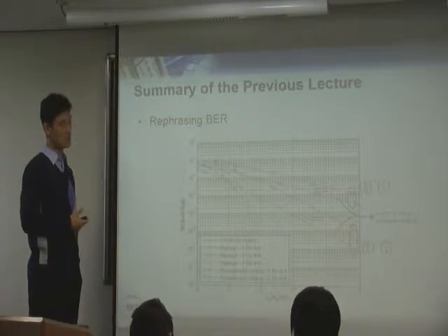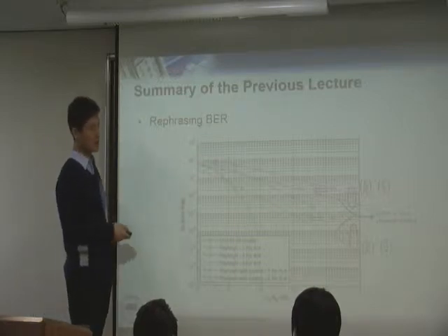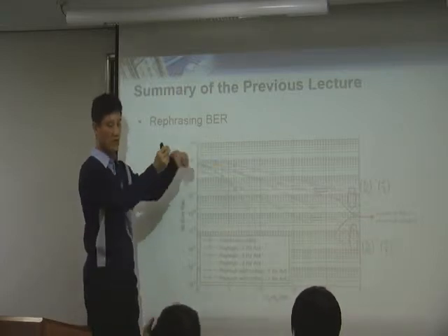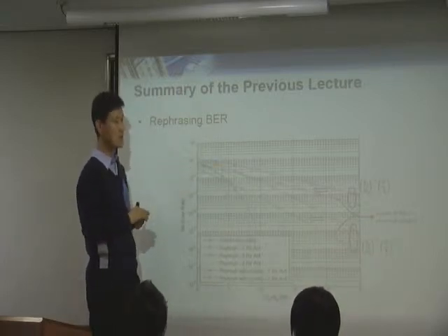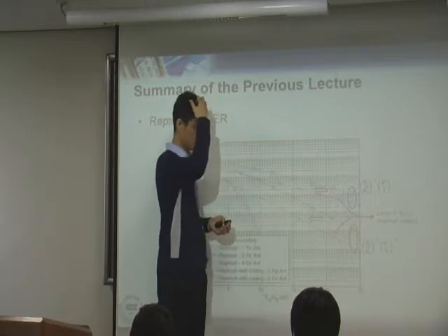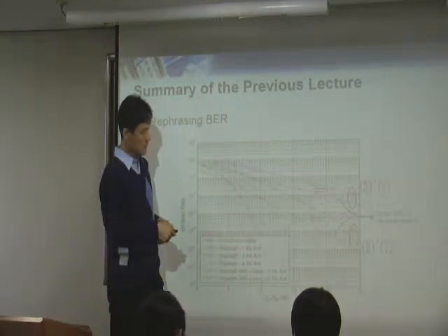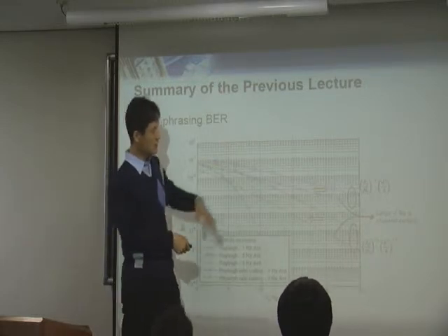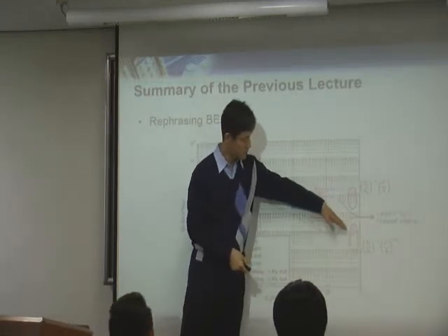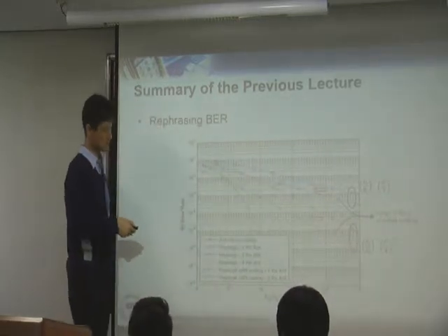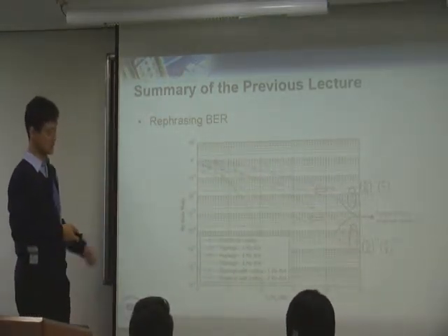So for example, if you use turbo coding, or some higher order convolutional coding, in that case you increase some coding gain, right? Because you are using another code with higher protection. In that case, the BER function is now shifted to the left side. Same way, if you use a higher protection coding with diversity order 2, we don't change the slope, but the whole curve is now shifted to the left by using the higher protection code.